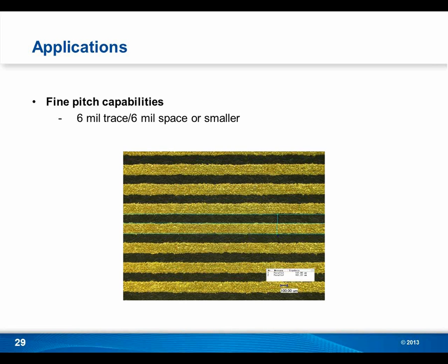Jan Willem wanted to ask, what kind of laser power and wavelengths are applicable to LDS? That really varies on the different plastic materials. Most of the laser systems that we have are operating in the near infrared area. Again, laser power very much varies with the different type of plastic materials. There's really no standardized answer to that type of question. So different plastic materials will require different laser power, different laser recipes or tools, as we call them.